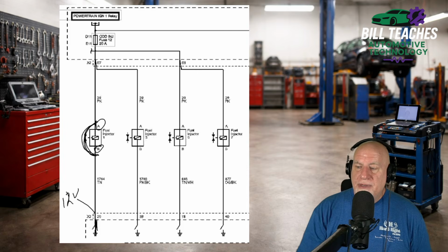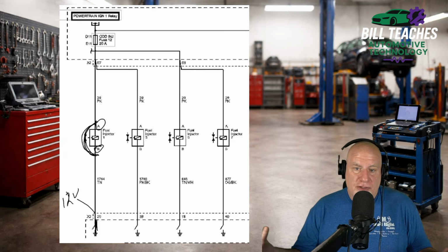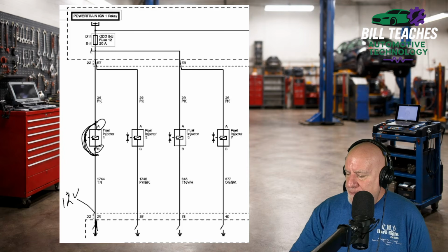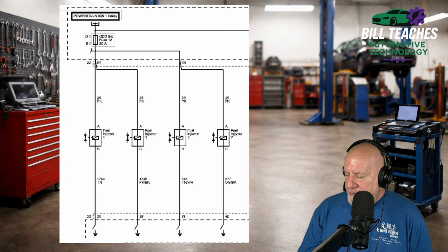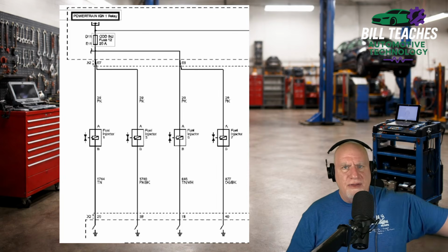So the fuse would not blow because we've opened the ground. We have opened the circuit, virtually stopping current flow, and that would keep the fuse from blowing. I hope that makes sense. Okay, so that's scenario 1. That's answering the viewer's question.